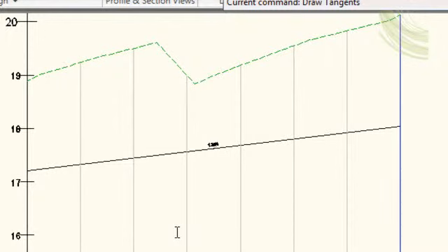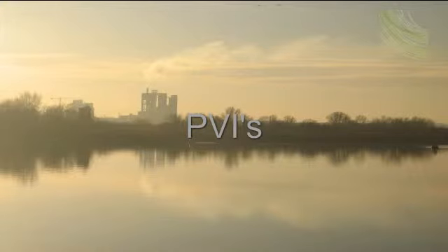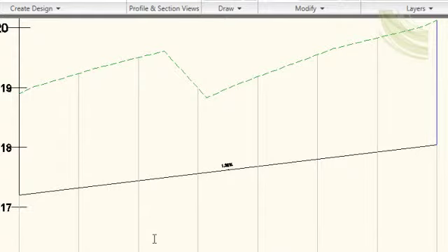In this video, we're going to show how to create a drop manhole on a sewer run. Here we're going to raise the sewer from 30 metres to 70 metres by 1 metre, leaving the lower part of the sewer intact. We are going to insert 2 new stations along the sewer run at approximately 30 metres.